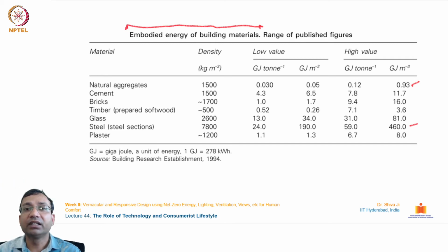You can utilize these lessons from this lecture, from this course, in your design projects and exercises. How well or how efficient you can make them by just changing, for example, just the material part of it. So instead of using bricks, if you use adobe based bricks or rammed earth bricks, how much energy you can save, how much embodied energy you can save right there.